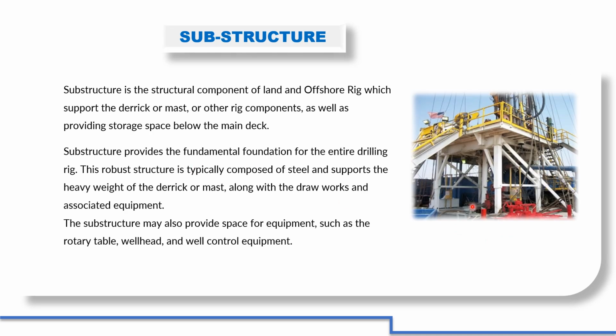The next is the substructure. This area, below the rig floor, this entire structure, is called the substructure. So what is the substructure? The substructure is the structural component of land and offshore rigs which supports the derrick or the mast. It supports the entire derrick or mast and all the equipment hanging in the mast, and the other equipment on the rig floor.